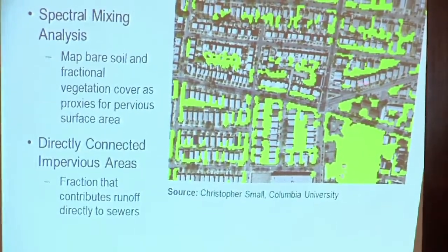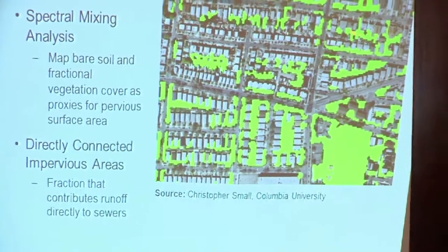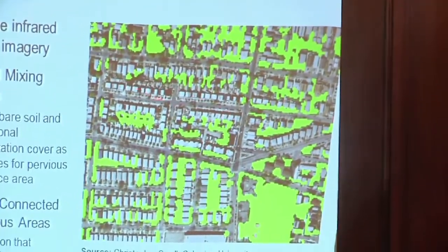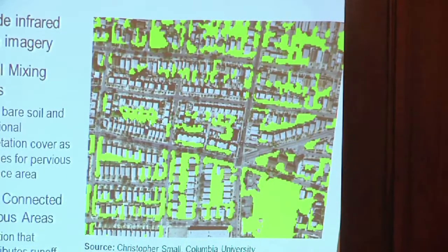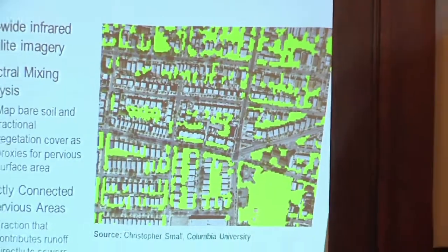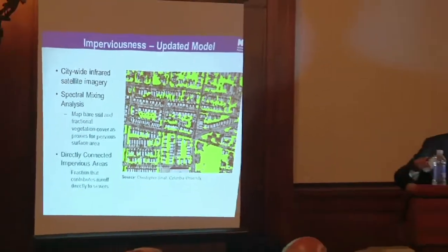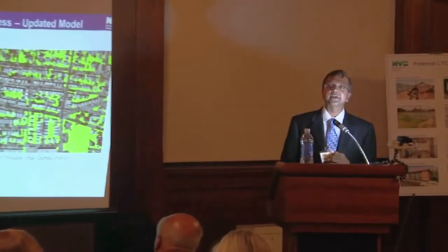And then once we identify them, the complementary pieces are the impervious areas. So what you see here, these are all the impervious areas within the system. These are identified as the pervious area. And what you see here as impervious is all what we call total imperviousness. It doesn't mean that every drop that is generated from these is reaching the sewer system. There are a lot of things that happen: potholes holding the water, there's seepage happening, there's water stagnating in the low-lying areas. It's not reaching the sewer system.